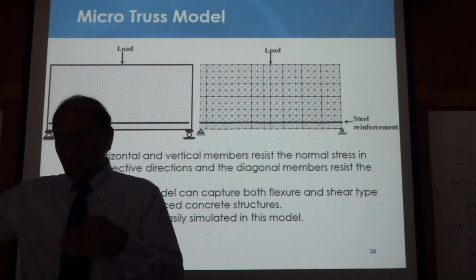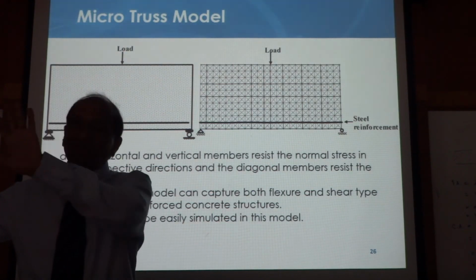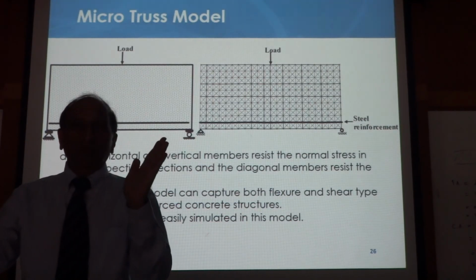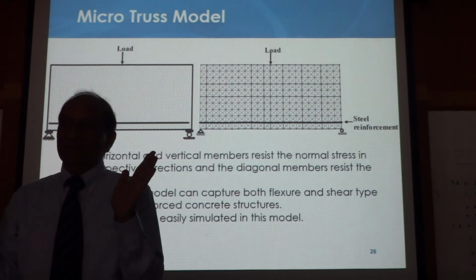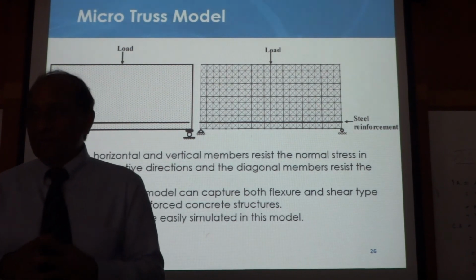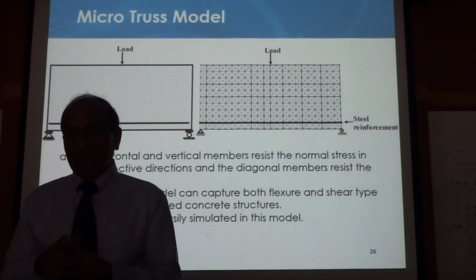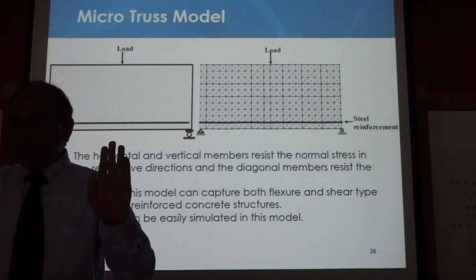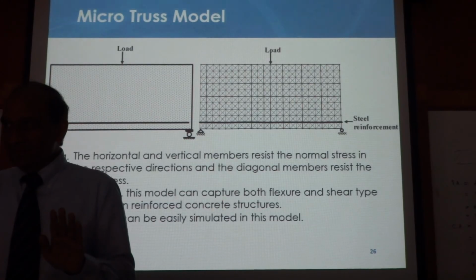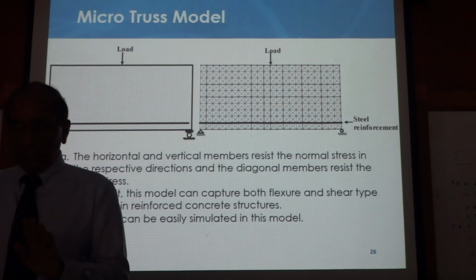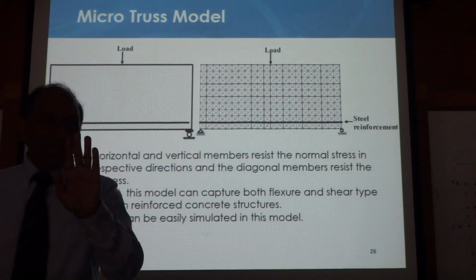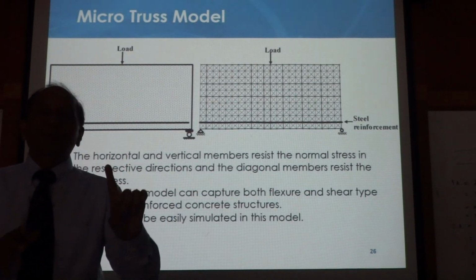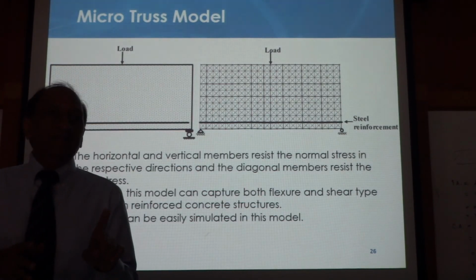Before cracking, elastic model, that's what we do normally. And then the second model in which we say all cracking has already happened. Intermediate we don't know. That is too complicated. There are ways to do that, some people do that. There are many software packages which can handle that, but it is not practical. So we can deal with two states. Just before cracking, one material, elastic stress distribution, elastic equations. And after cracking, the post-cracking situation, all concrete in tension gone, only concrete in compression remaining, all tension taken by steel.